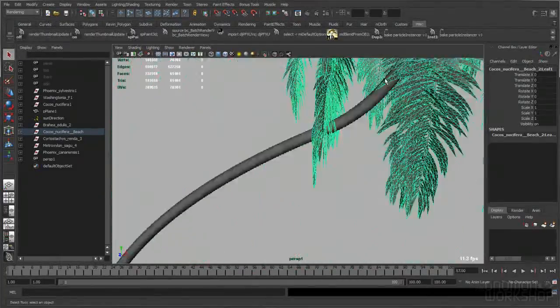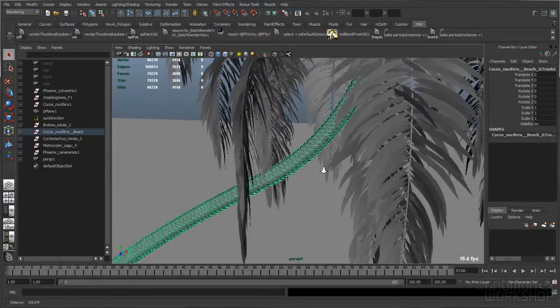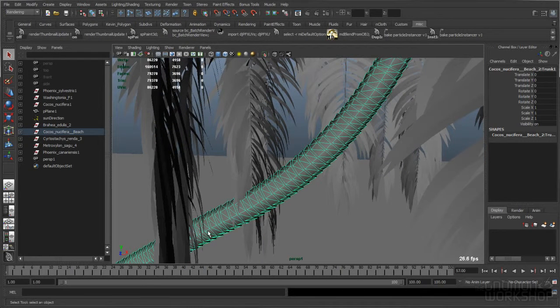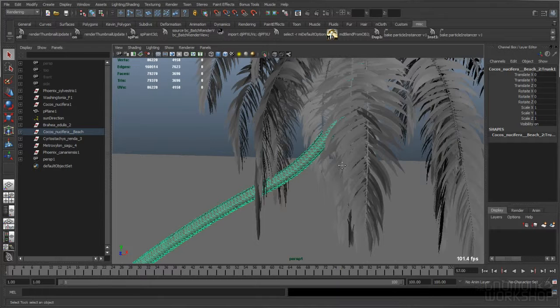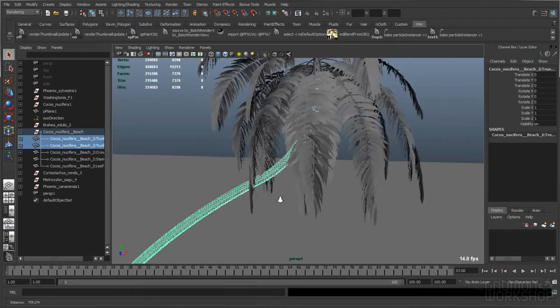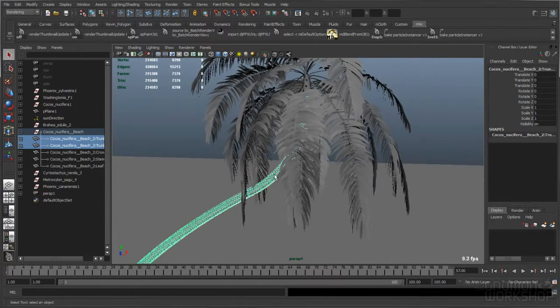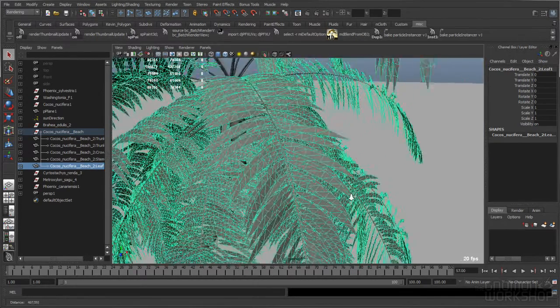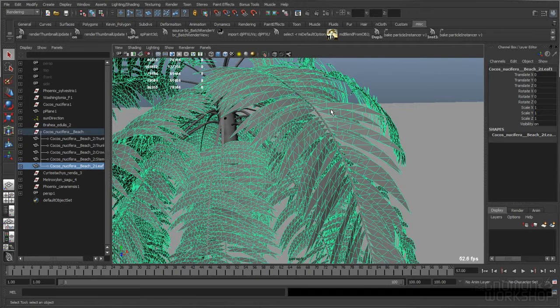We can see also with the tree, as far as the polygon count, that it has some detail on the edge of it. You could obviously simplify that trunk out and do it all via texture just to save some polys, because clearly the trunk is adding up to about 7,000 polys. But as you can tell by now, to me that's not a lot. So in here, since they have that shape, I don't need to worry about a cutout opacity.